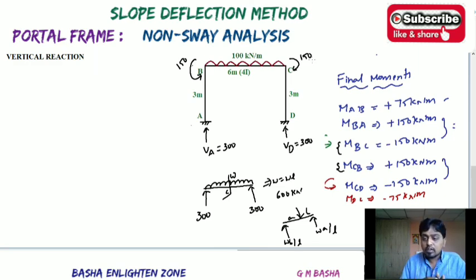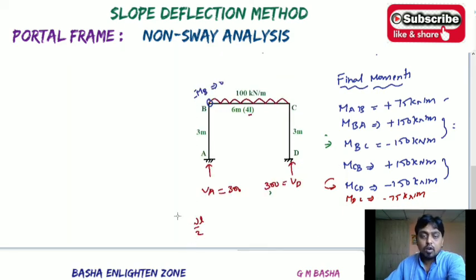While solving so many problems, you will know in what way you have to calculate the vertical reactions. But whenever symmetrical conditions happen, you can take the vertical reactions directly, like you can distribute the load based on the simply supported beam condition only. So you can solve this one manually also. All these things you can learn at the basic level itself in strength of materials and engineering mechanics.